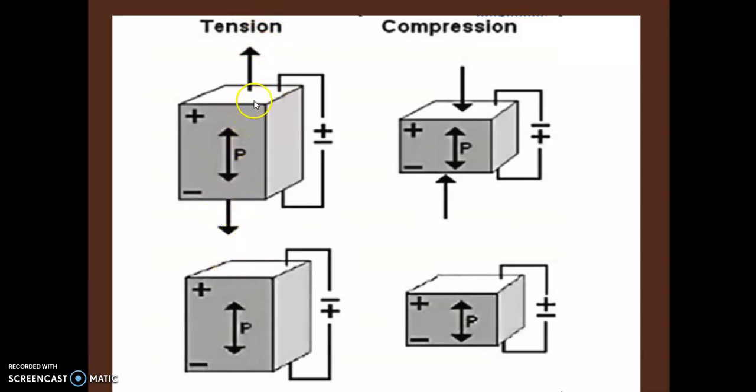In short, you are pulling these two faces, one upward and the one below downward. Imagine stretching rubber like that: you are putting this mechanical strain, tension, and pulling these two faces. As soon as you apply mechanical strain, charges will be created because the positive charge and negative charge will be separated.